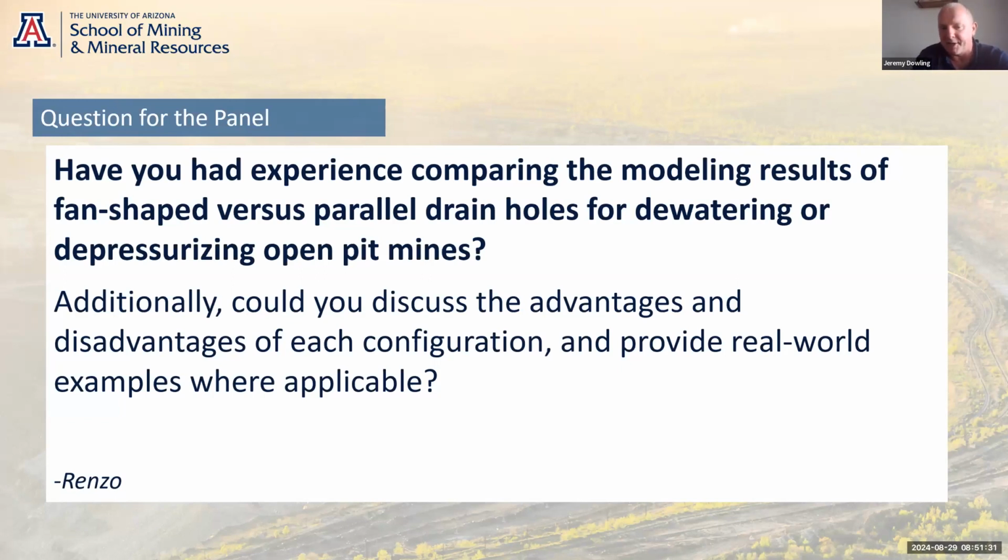So you don't just drill a random kind of half cartwheel shape, but you orient all of the drains in a splay through the fabric and the structures so that you hit more permeable features and get more drainage. And if there are bad acting structures behind the slope, then you get to depressurize those as well.